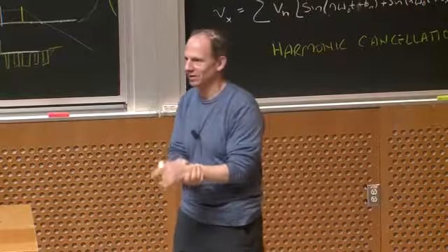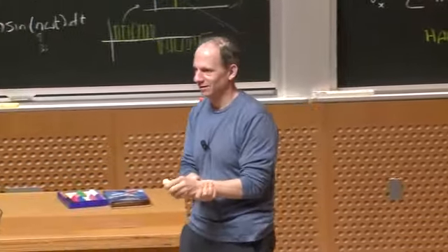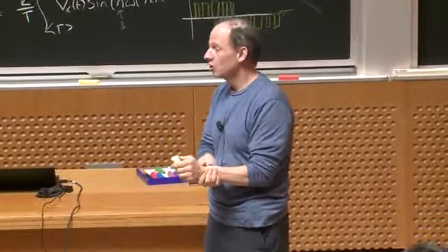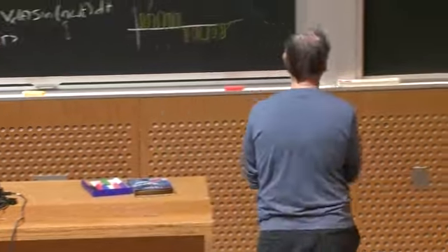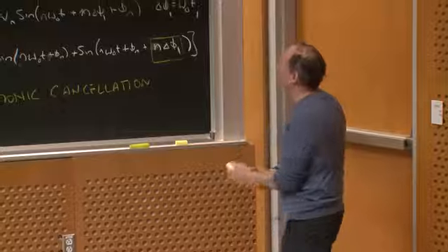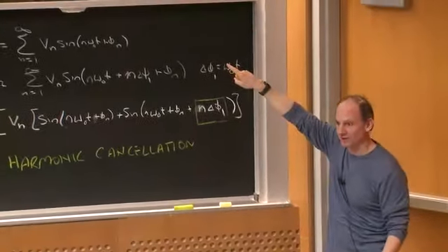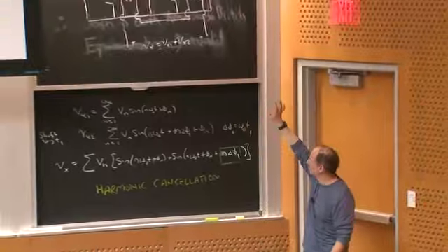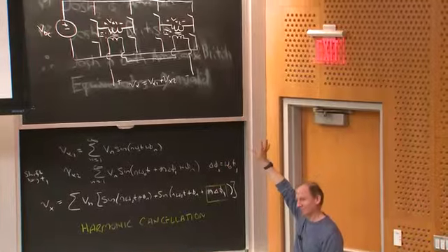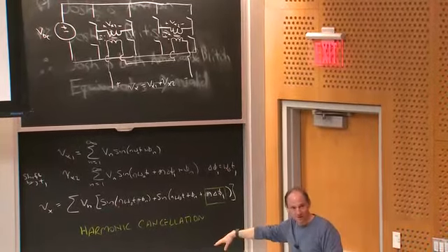Excellent question. Sir, do you also use this trick to just increase the AC output voltage? You could, yeah. So what would be another benefit of this? Right, the Vx has twice the amplitude of VDC I could synthesize. And that's just for this particular implementation, which is only one way to do it.